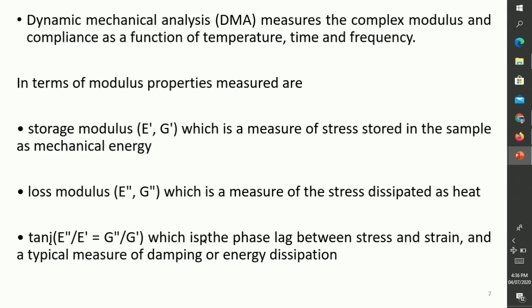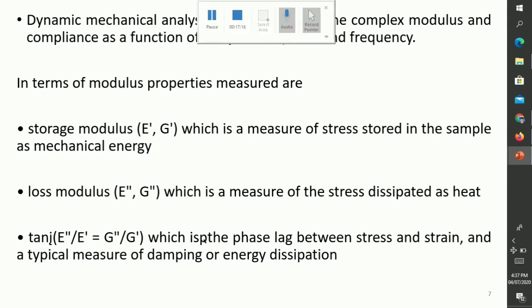So these are some of the important aspects of dynamic mechanical analysis, which measures the complex modulus and compliance as a function of temperature, time, and frequency. This would also help us in the analysis of thermosetting materials.